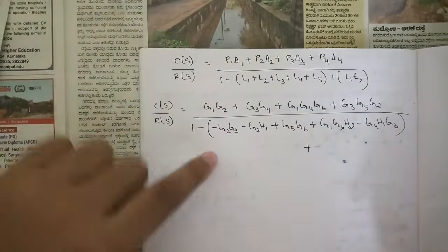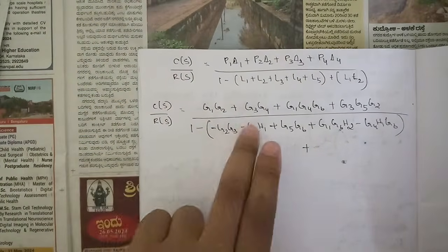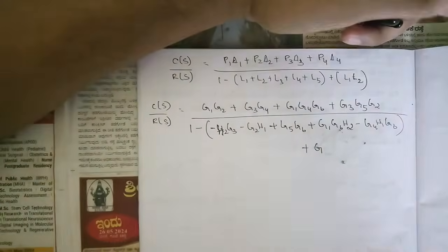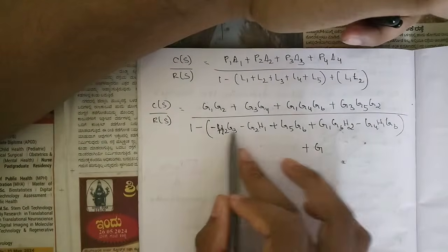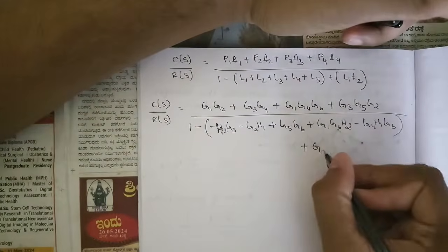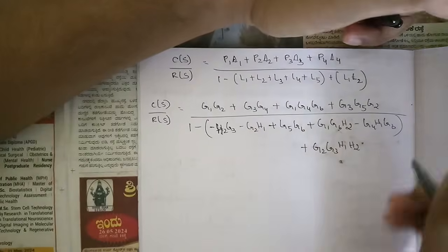So the value of L1 is G2, G3, value of L2 is G2, H1. If we multiply this, minus into minus is plus, so it would be, sorry, this is H2, G3, okay, not G2, G3, H2, G3. So our final answer is G2, G3, H1, H2, okay.